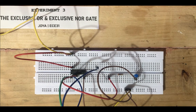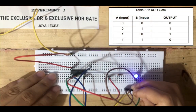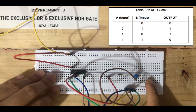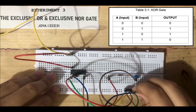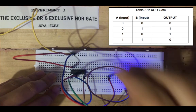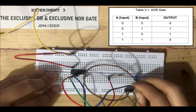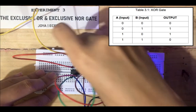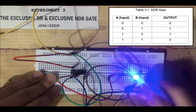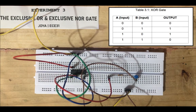When connected to a 5-volt power supply and inputs A and B are both 0, the output is 0. When only B is 1, the output is 1. And when A is 1 and B is 0, the output is still 1. But when both A and B are 1, the output is 0.